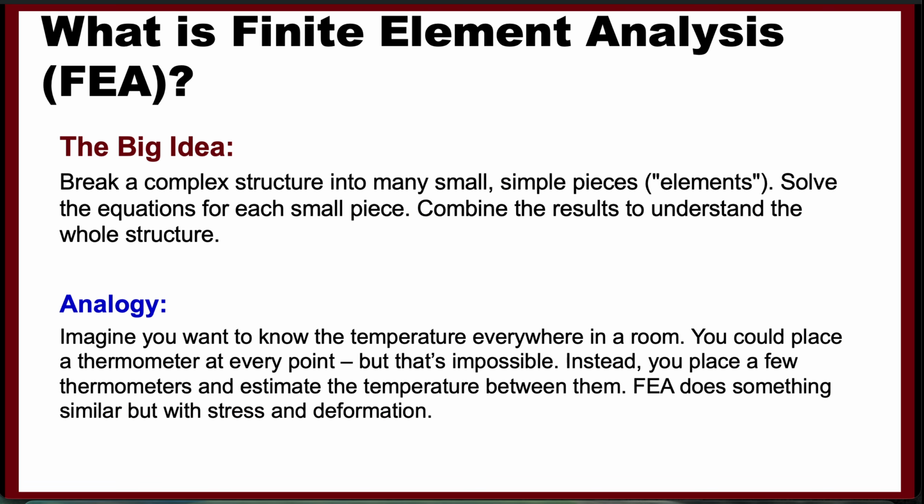The idea of finite element analysis is that we are going to break a very complicated structure into small elements and then solve the equations for each element separately, and then we're going to combine the results to find the results for the whole, complicated structure.